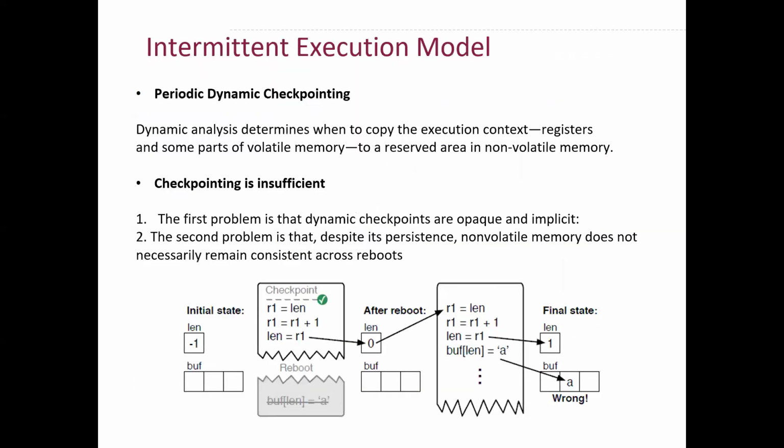Now, let's come to the intermittent execution model before you go into DINO, because the intermittent execution model is something which is persistent across many research papers. We know that after a reboot, execution resumes at the checkpoint. Since we are using checkpointing, your execution will resume at a checkpoint rather than main. And that is exactly the core idea behind any intermittent execution model.